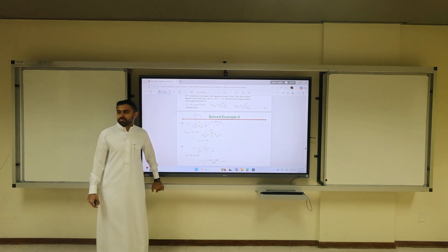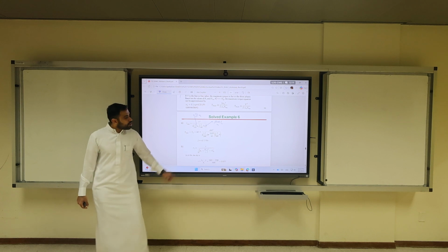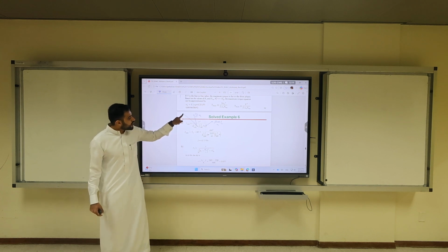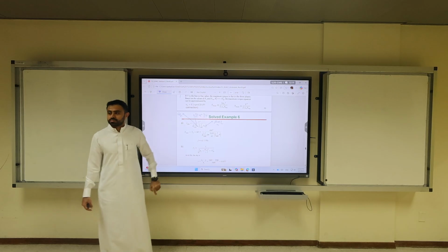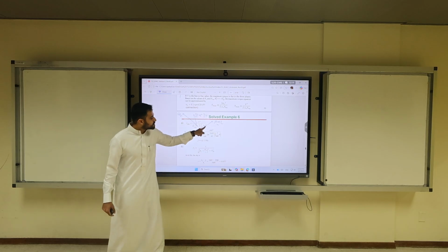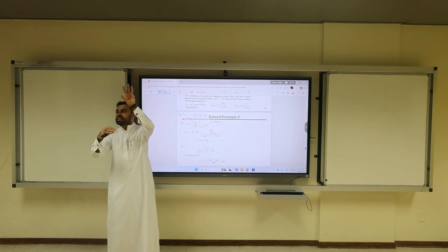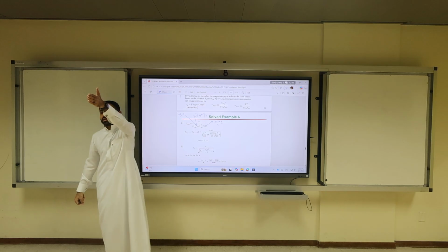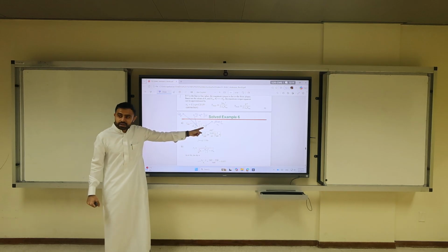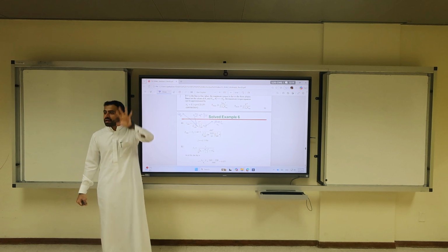Why? Trick. Because omega S is calculated at 60 using this formula, 2 pi. What is NS? 120 times 60 over 2. And what is X equivalent? It is calculated at 60. So he divides by 60 and he multiplies by the needed frequency. This is a trick in machines. The F over 60 trick. What's the F over 60 trick? Instead of recalculating X equivalent, recalculating omega S, you just multiply by F and divide by 60.